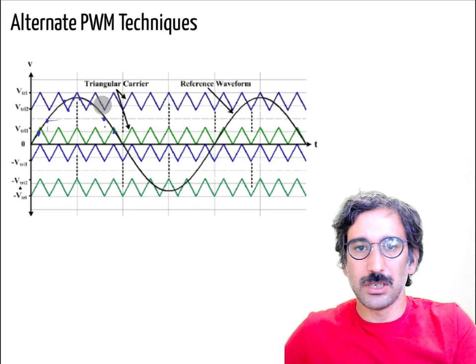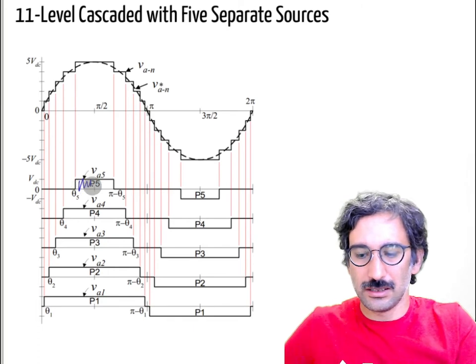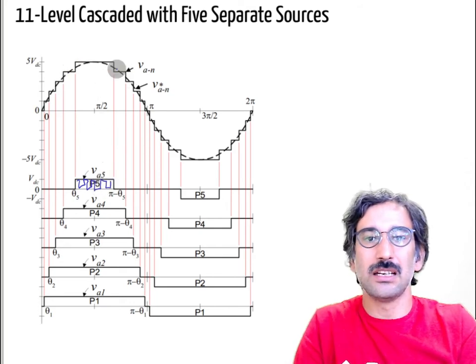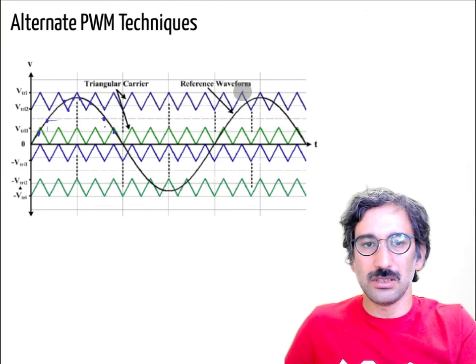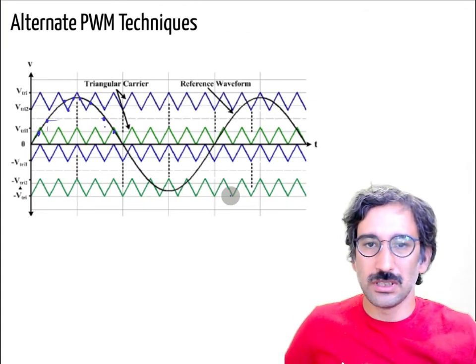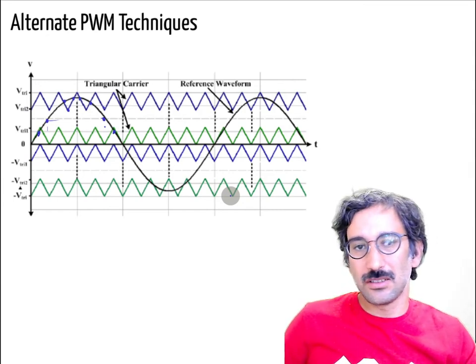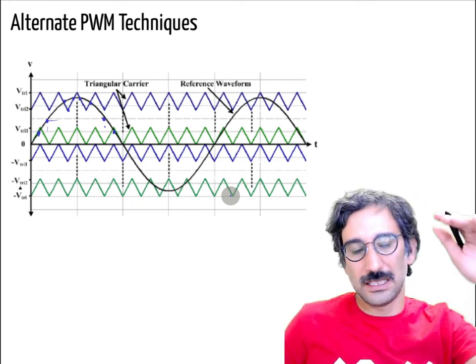Normally you have a much higher frequency. The last one can generate PWM signals in the last stage, so you will have a much nicer voltage output. So the easiest way to generate PWM is to generate different triangular waveforms with the same frequency but different offsets.